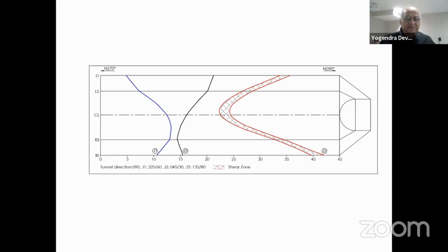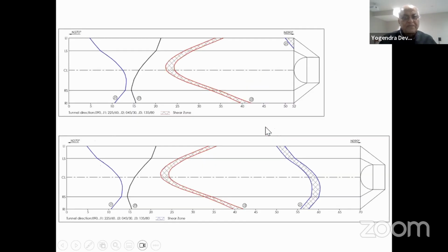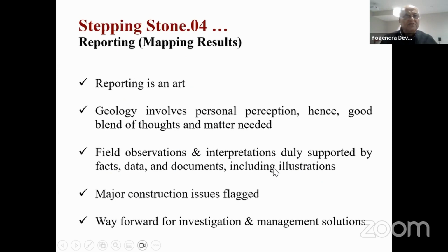You can see that this zone we have seen in this particular place. Now, you can tell the tunneling crew that this zone is likely to continue. You are at 25 meters, and you can see it is going up to about 20 meters more, up to 40, 45 meters, and this is the place where it is coming, so they can plan their excavation, then plan their design. Another example: when you have crossed this zone, you cut another one in this particular corner, you use the app, and you can tell that this zone will continue like this, which can be useful to the tunneling crew.